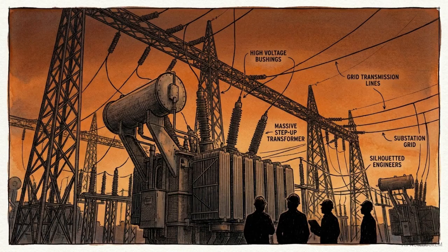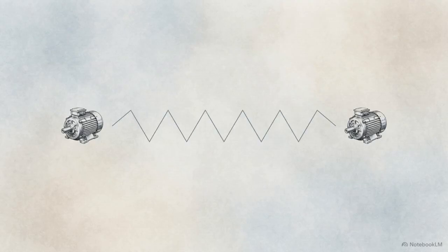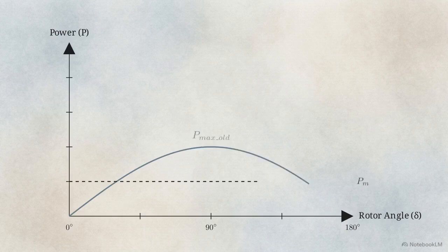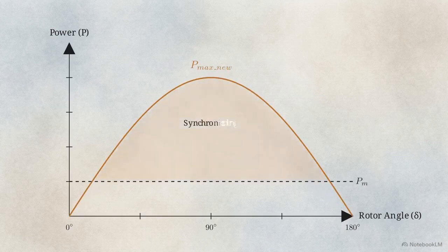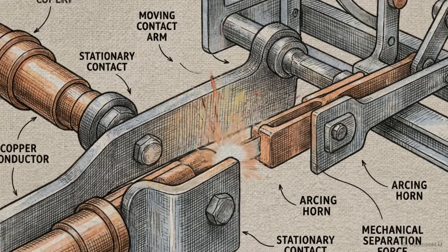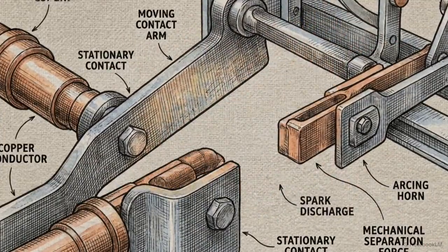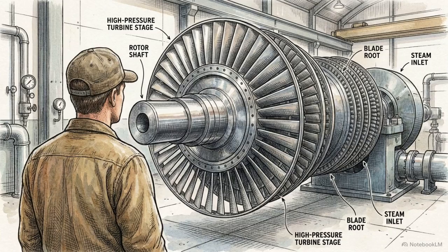Engineers design the infrastructure to withstand these multi-machine transients through physical interventions. Reducing transmission impedance keeps generators electrically closer together. Lowering impedance increases the synchronizing power transfer margin, allowing the system to better handle disturbances between different grid areas. Fast-acting protection relays and circuit breakers are also critical, as they minimize the time a fault stays on the system. Physically reinforcing the grid and shortening fault durations reduces the kinetic energy rotors must absorb, preventing them from slipping poles.